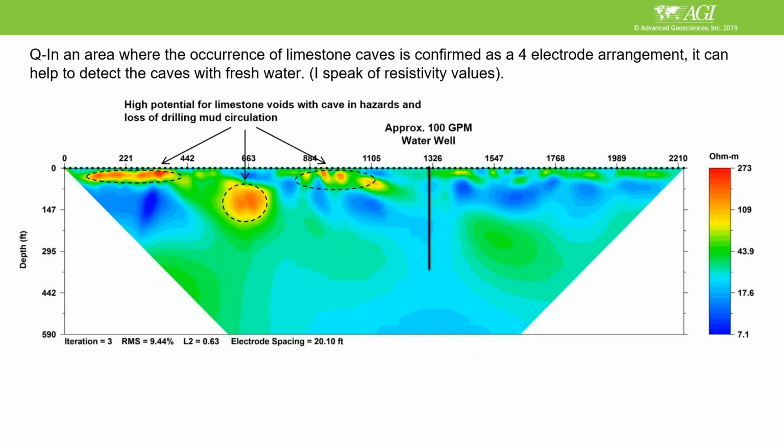And then you combine it later with the strong gradient, because strong gradient gives you a high signal, since the current electrodes are outside, like a Wenner or Schlumberger. So in that case, you combine that with the dipole-dipole, you get a joint inversion, and you get that section. So whatever section you're getting, for instance, you're getting sections like here, and these sections here.